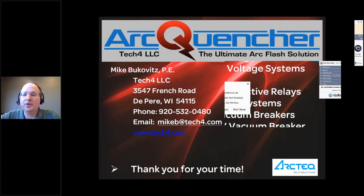By the way, I see another question here from William Shiri. It says, for an older facility, would implementation of arc flash relays and sensors be cost prohibitive? How much time is needed to install on a typical MCC? That's a great question, and the answer is that arc flash relays are not the costly part. The arc quencher is the more costly system. Again, the average cost of an arc quencher system is $75,000 for a low voltage system. That seems expensive until your equipment is catastrophically destroyed, or someone's injured or killed. All of a sudden, that seems very inexpensive. But if we're looking at just arc flash relays and sensors alone, the cost of the relays and the sensors is comparatively fairly small. An individual point light sensor is less than $200.